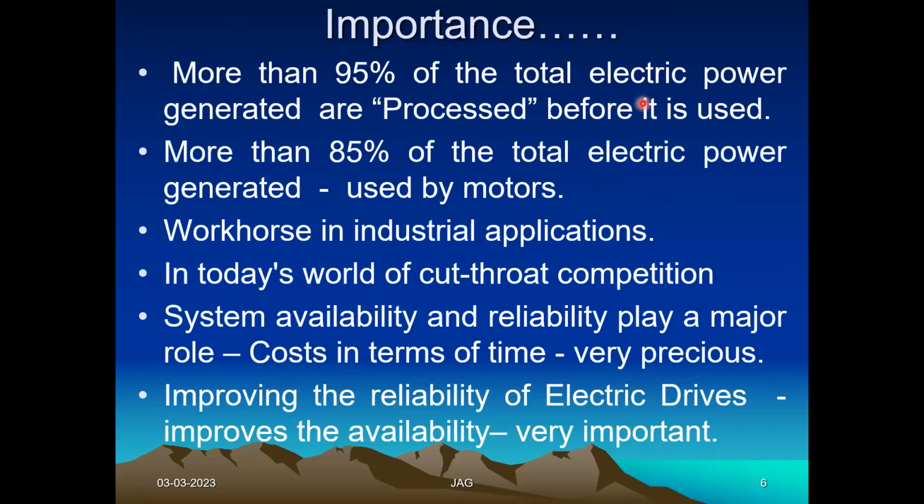More than 95% of the electric power is processed before it is utilized. This is what I have told you today. Whatever load you take, whether it is a fan, even an ordinary induction motor fan, when regulated through a solid state regulator, that is a power electronic solution. The solid state fan motor speed regulator is purely a power electronic solution. Conventionally, we had resistance-based speed regulation, which dissipated much more power, wasting much more power. The size was also very bulky.